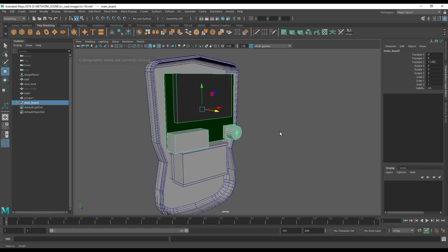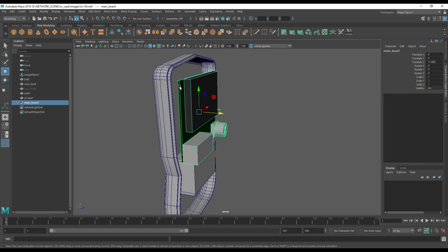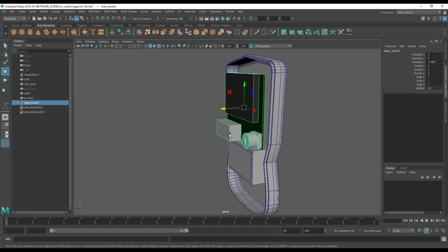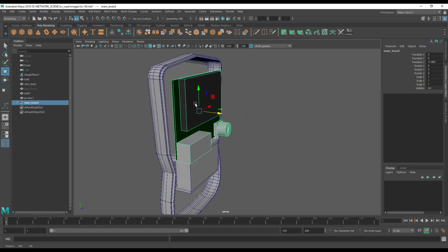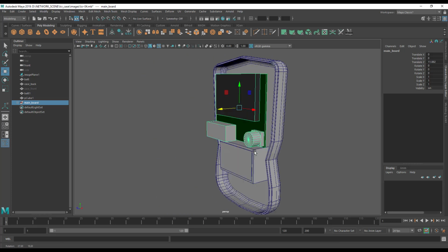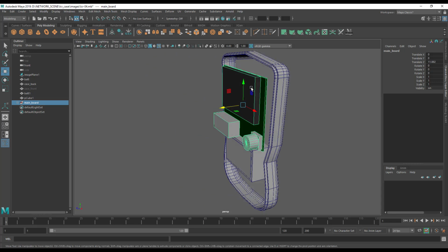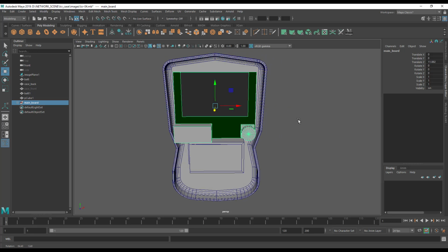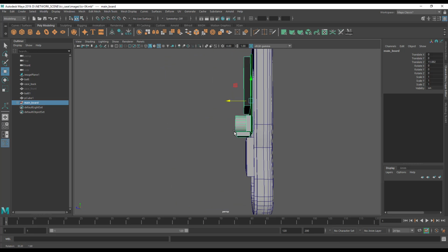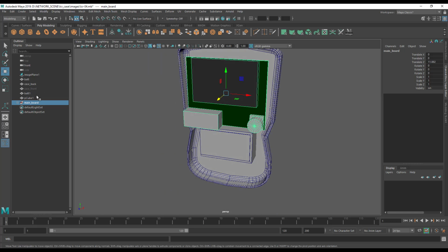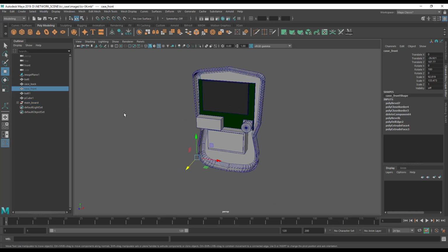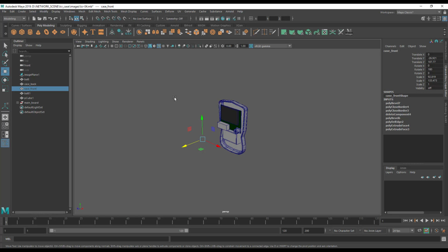Let's bring the front of the case in. So the case moves back, and the button, the ZIF socket and the screen, so the button will be proud of the case, the ZIF socket will be proud, and the screen will be just on the border of not sticking through. We'll still have to cut a hole for it. That should also allow us to use the case to help secure the battery. So let's bring the front of the case back, Control 1. Not Control 1, sorry, that would isolate it, Shift H.